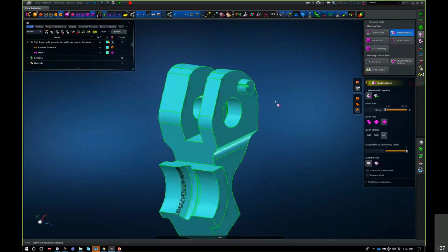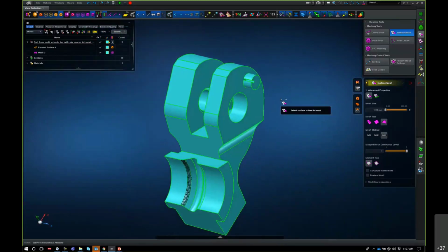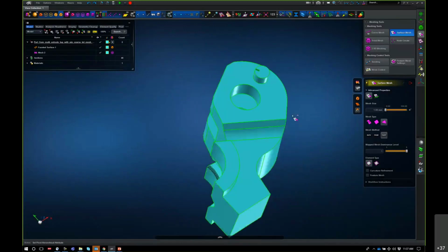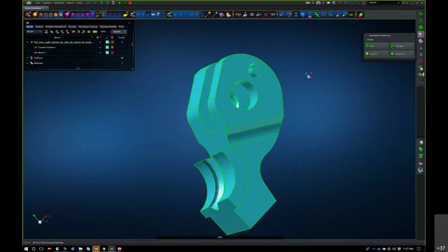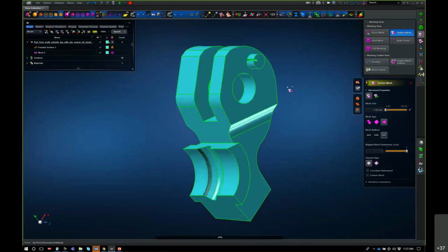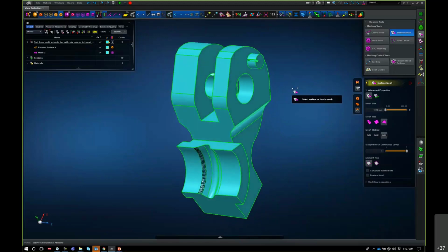So now that allows me to work with facet bodies. As long as I'm working in Apex and remeshing my model, facet bodies are just wonderful with the smoothing option turned on. I can do all kinds of really, really coarse meshes and still work with remeshing my model. Of course, not all geometry tools, but Boolean, surface split, add vertex, all these things now work on this geometry. So depending on what I'm doing, depending on the kind of model, especially if it's a model that came from CAD, I can work with this geometry. It's wonderful stuff to work with. I can export it and bring it into other Apex sessions.